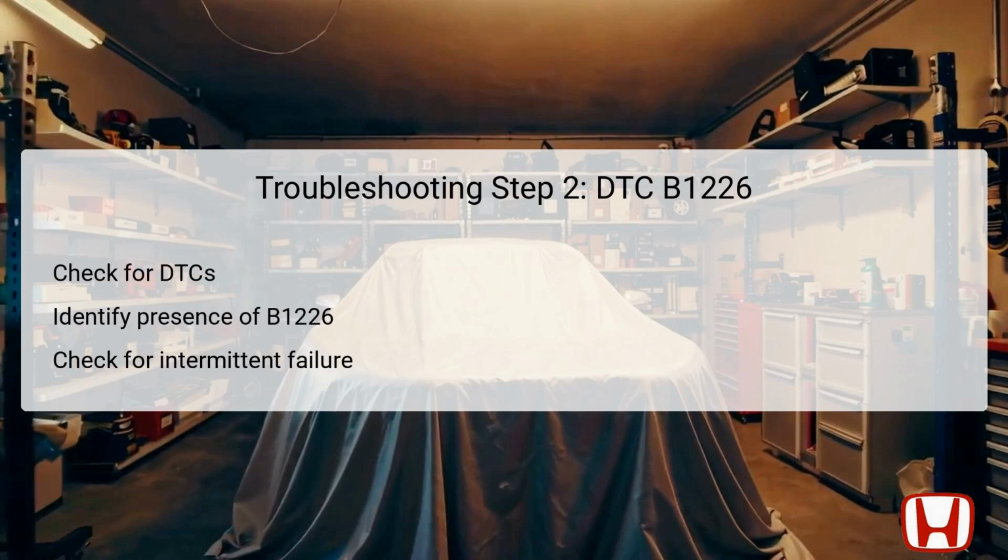In this second troubleshooting step, the technician should check for any diagnostic trouble codes that may have reappeared after performing the self-diagnostic function. If DTC B1226 is indicated, this confirms that the issue is still present in the system, prompting further investigation. If DTC B1226 does not show up, it suggests that the failure could be intermittent. In such cases, it's essential to assess the in-car temperature sensor circuit for loose wires or poor connections.